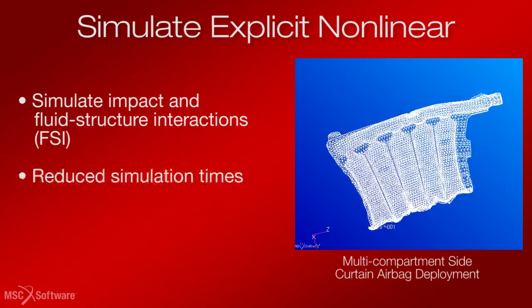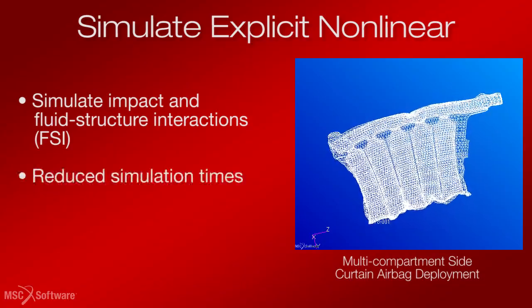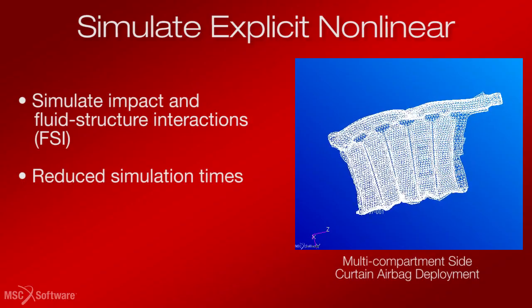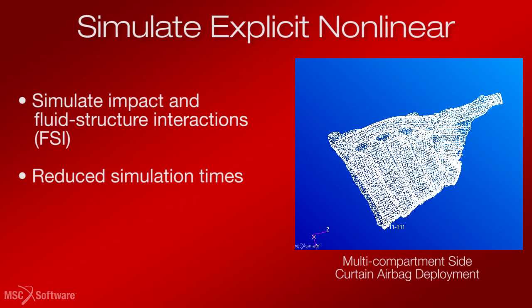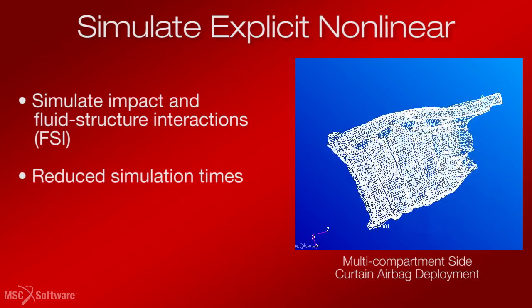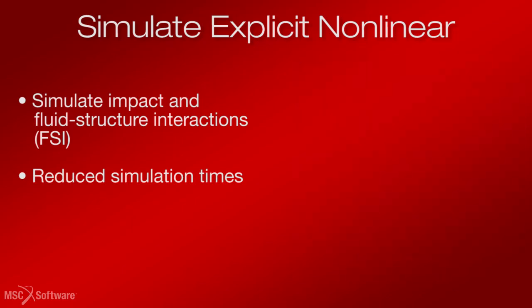Simulation times are greatly reduced for FSI analyses like drop testing of fluid-filled plastic bottles, fuel tank sloshing, and airbags through distributed memory parallel solutions for adaptive Eulerian meshing of the fluid volumes.